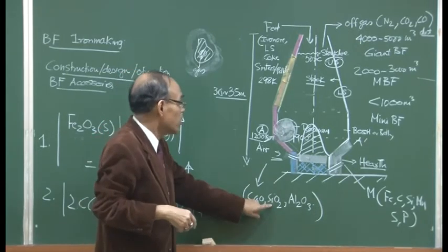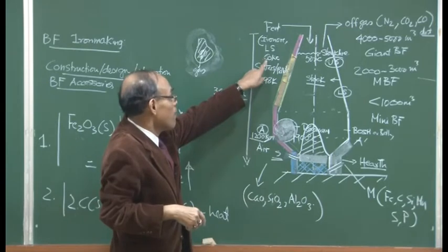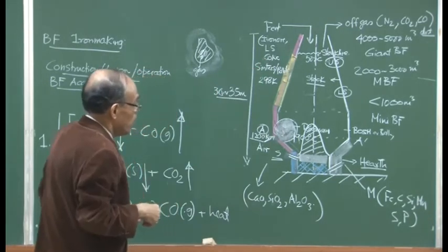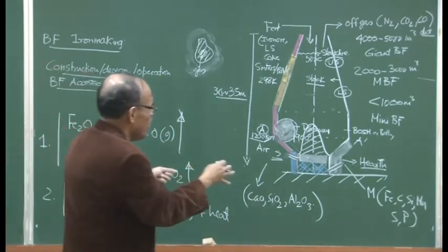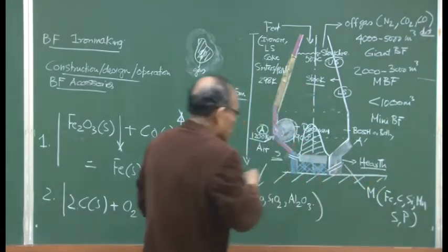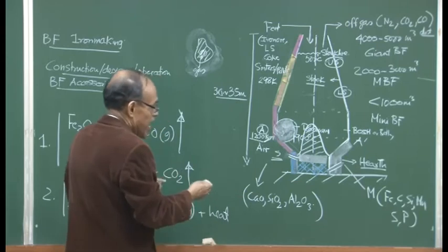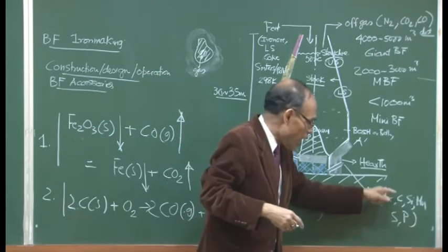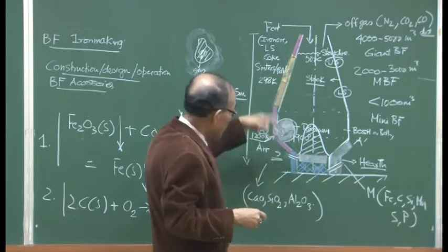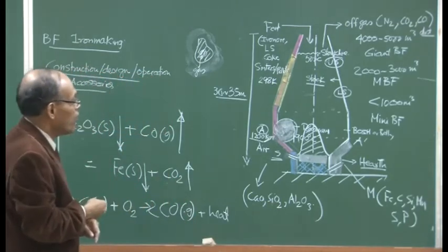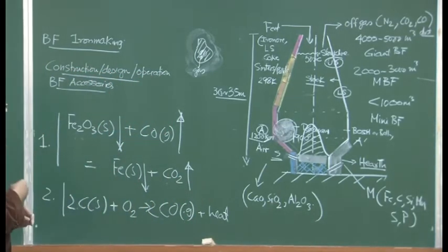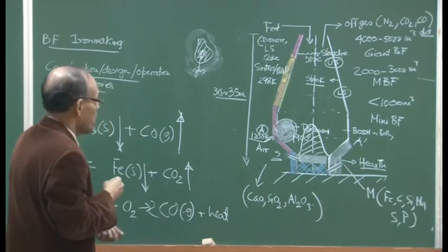So this sulfur, silica is also a part of it comes from coke. So these are roughly very basic elementary level compositions, or constituents which make slag and metal. We will see how the composition changes along with the processing of iron inside the blast furnace, and the blast furnace operating practices a little later, which you need to develop enough understanding of the subject.